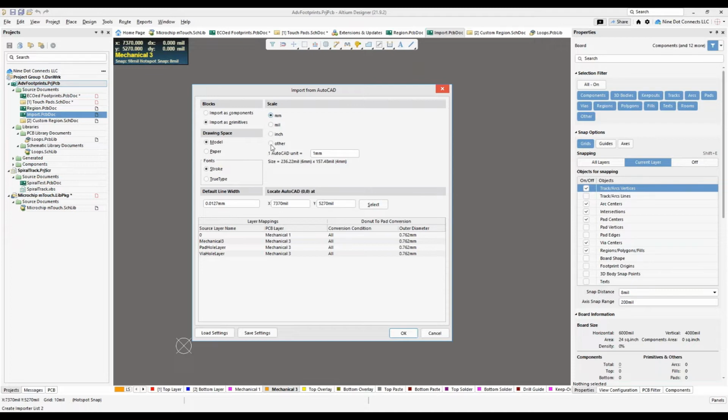Because the minute we look at this, where do our eyes go? They go right to this thing called the one AutoCAD unit, and we think that this is what we're selecting over here when we hit these radials. But these first three radials over here really have nothing to do with this AutoCAD unit over here. What it's really talking about is the other. Now, it is kind of showing this because AutoCAD does use the units and it's kind of giving you a hint as to how it's going to translate it.